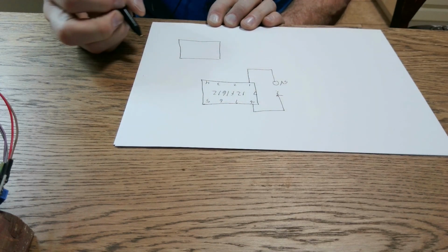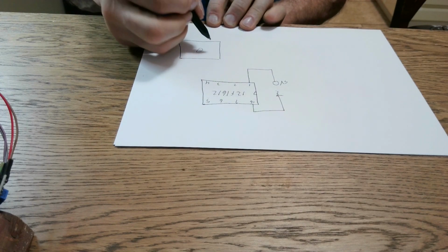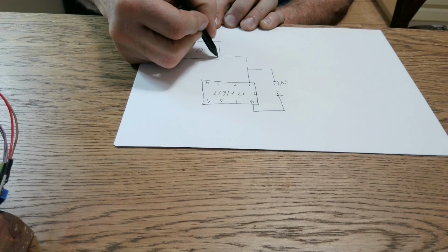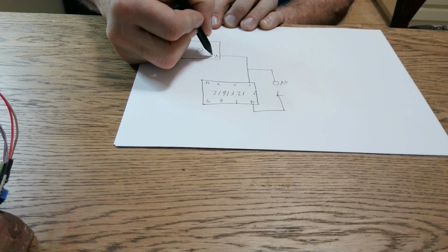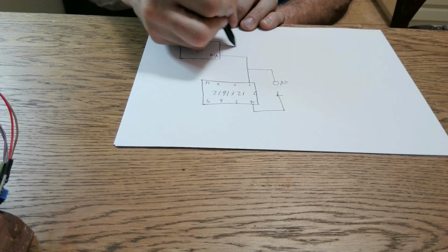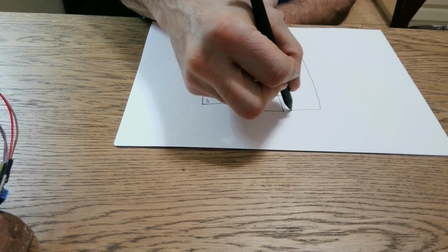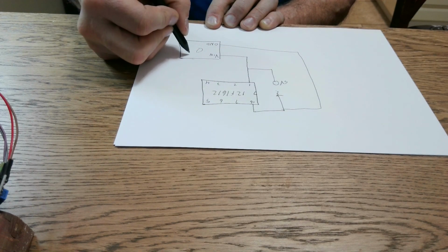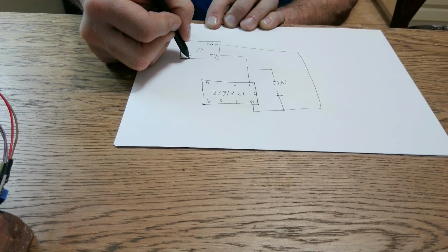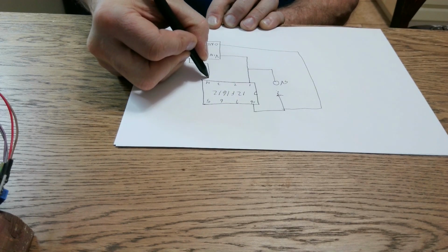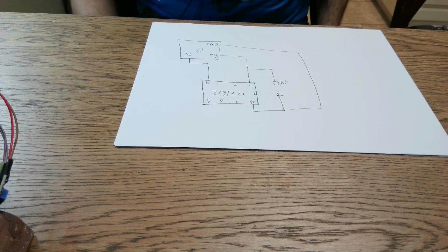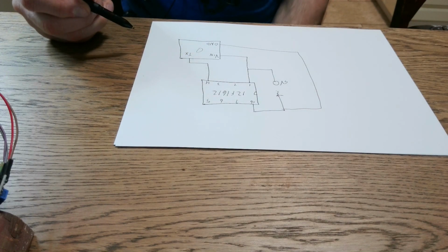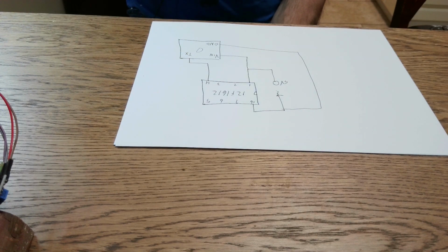The GPS unit is the same thing. It has 5 volts right here, and I believe it's VN on this particular module. It also has a ground running to the ground connection. Nice and simple. And there's a data line known as a TX. That is the UART communication line that I will be acquiring my content from. So this is an input on pin 4, and I'm acquiring all the information I need right through that.